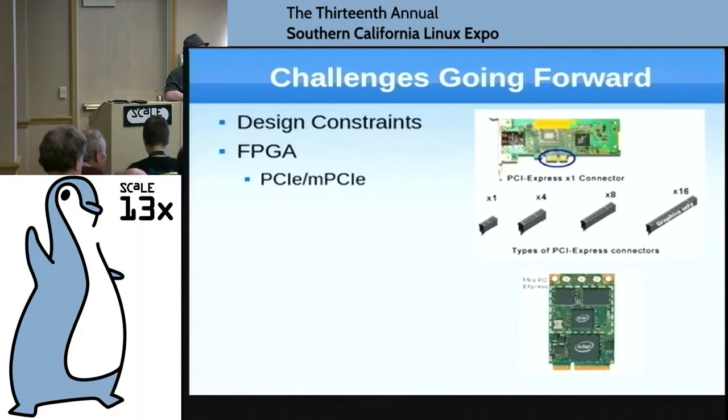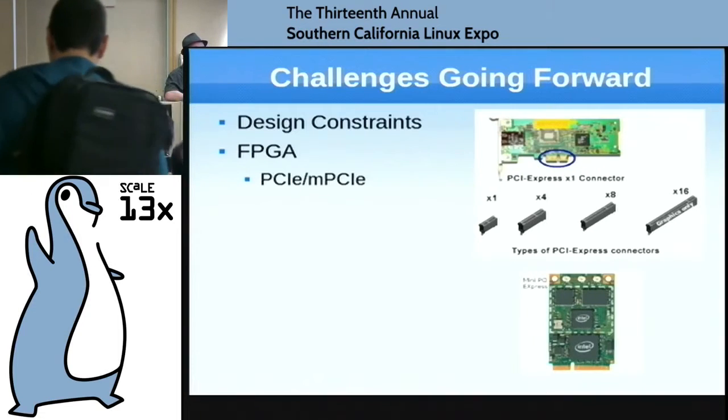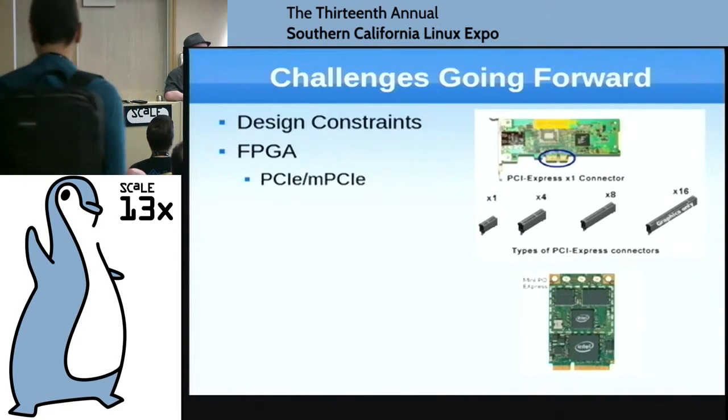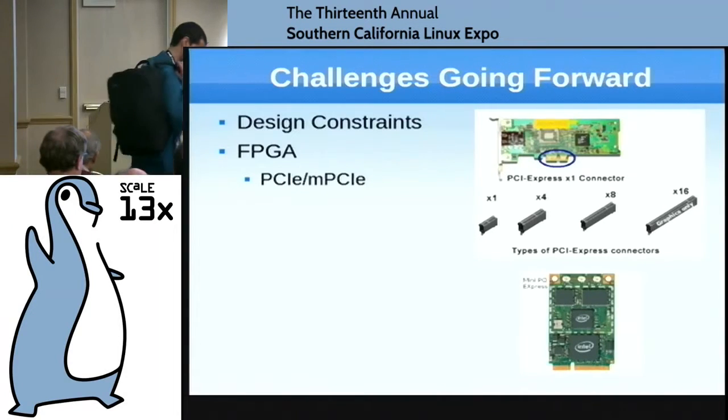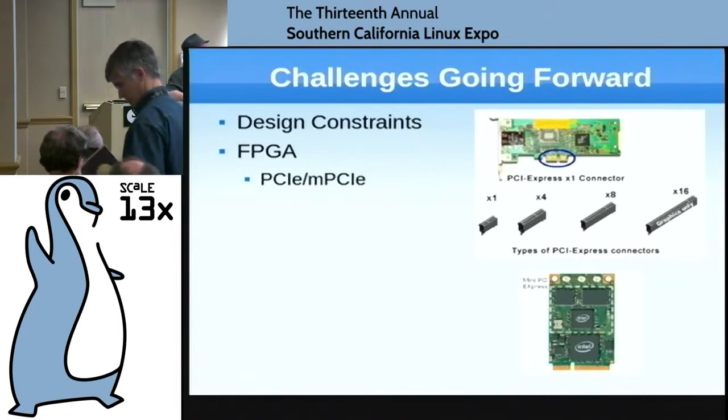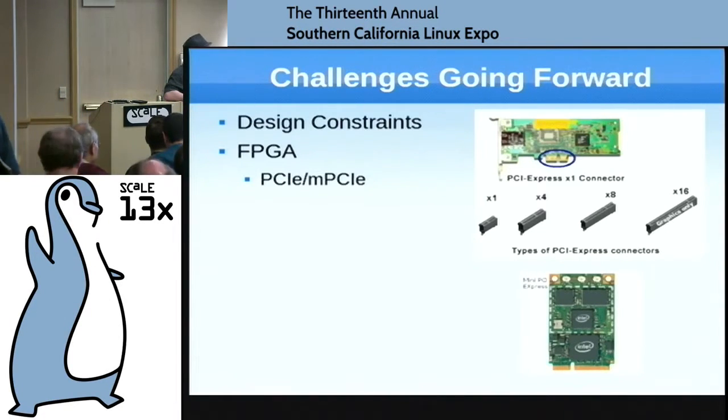To debug and test these, they are differential pairs. They have to have matched lengths, matched impedance, and they operate at very high speeds, which puts them out of the reach of most people to create open tools to debug these items. It's important because there are a lot of libraries already existing for FPGA that already support PCIe, and all you have to do is load that library and create your own software for a specific use case.